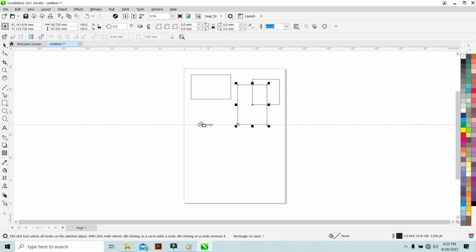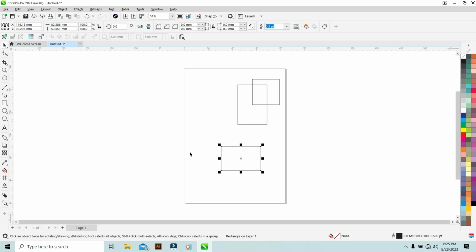I'm going to show you another thing. I'll select the big tool and bring this one in here. Now I want to draw one square, but my center point should be here. In that case, what should I do? I'm holding my Control and Shift keys together, then I'm going to draw in here.